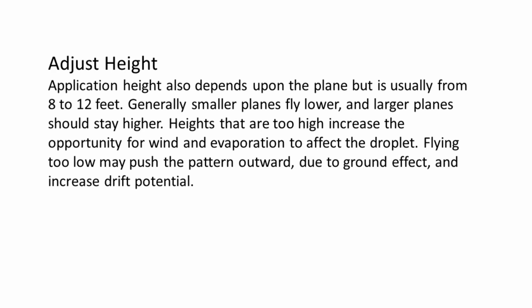Adjust height. Application height also depends upon the plane, but is usually from 8 to 12 feet. Generally, smaller planes fly lower, and larger planes should stay higher. Heights that are too high increase the opportunity for wind and evaporation to affect the droplet. Flying too low may push the pattern outward due to ground effect and increase drift potential.